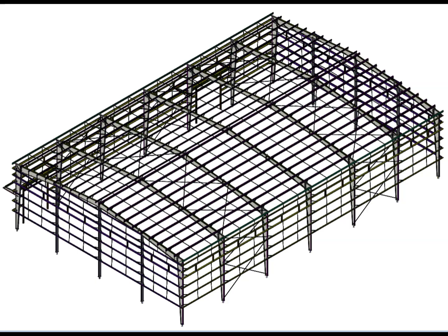But we still have one important question left. What exactly does the girt do? Let's summarize its key functions. Let's quickly summarize the most important functions of a wall girt. First, girts provide support for the wall cladding system. They create the structural support locations where the wall panels can be fixed according to the project detailing. Second, girts help transfer the forces acting on the wall system into the supporting structural framing.